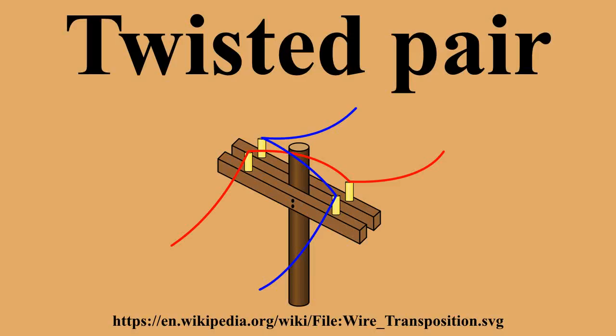The code before the slash designates the shielding for the cable itself, while the code after the slash designates the shielding for the individual pairs. U equals unshielded, F equals foil shielding, S equals braided shielding, TP equals twisted pair, TQ equals twisted pair with individual shielding in quads.